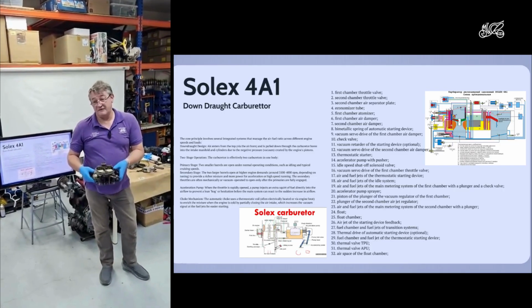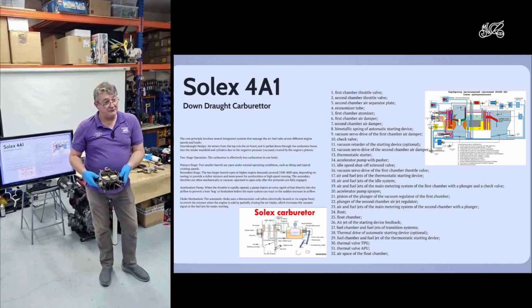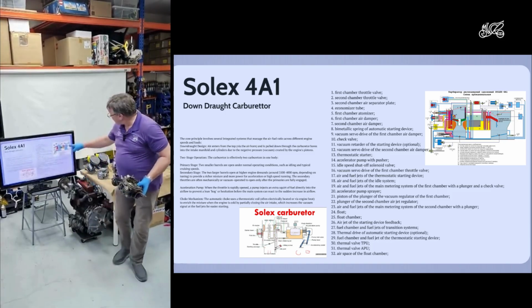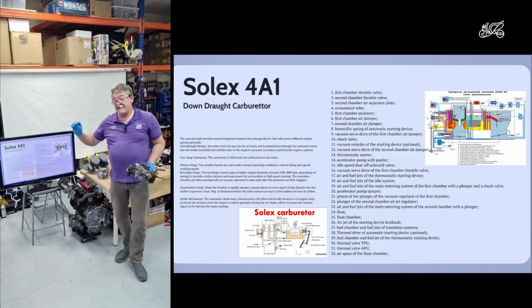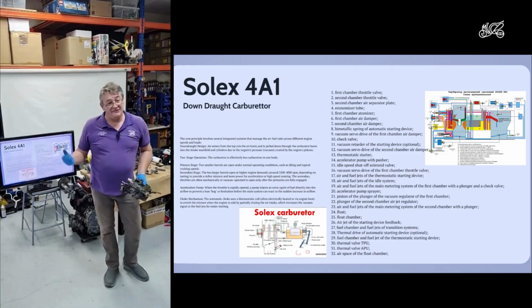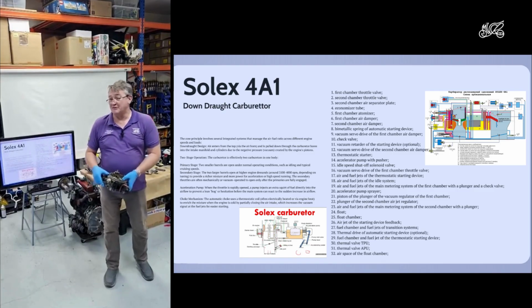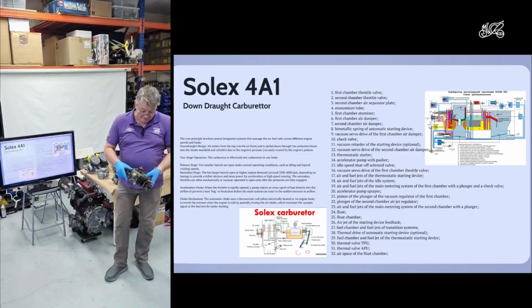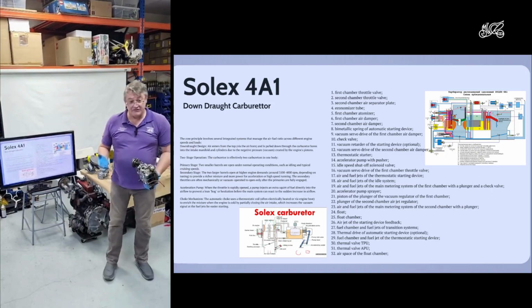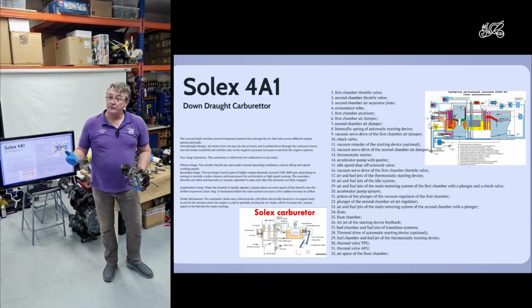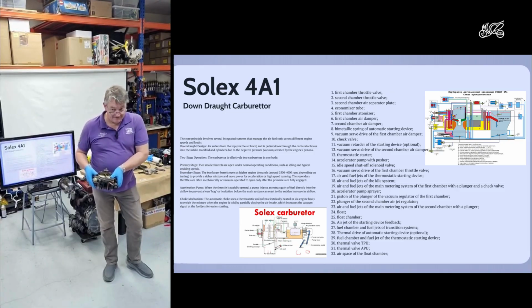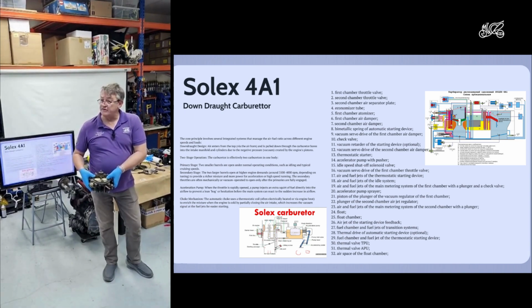And the worst thing for any carburetor is dirty fuel. Because inside this thing, there's lots of little passageways, yeah? And if it gets dirty fuel once, then half those passageways are blocked up, and then you really struggle to make this thing work. The other thing which I don't like, especially with modern fuels, is being stored. So if you keep a car for 3 years and then try and start it, with modern fuels, often there's a lot of corrosion inside this thing.